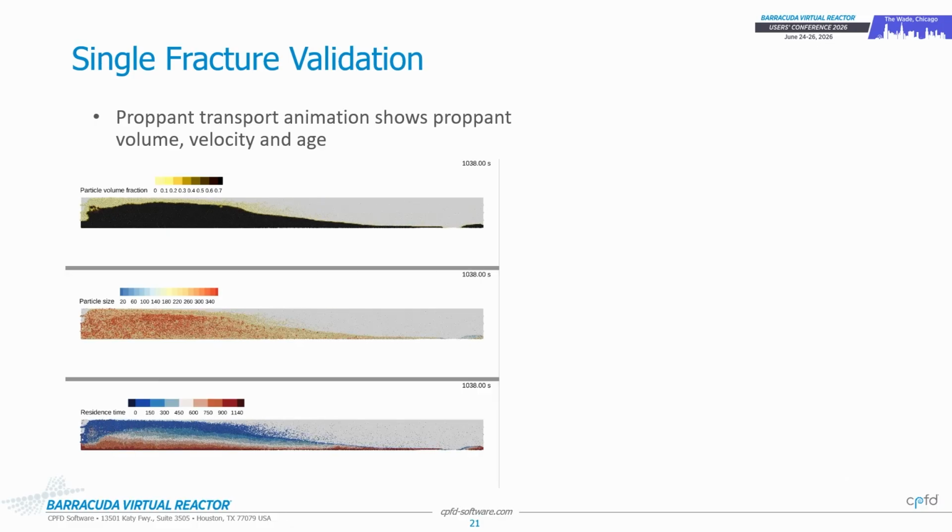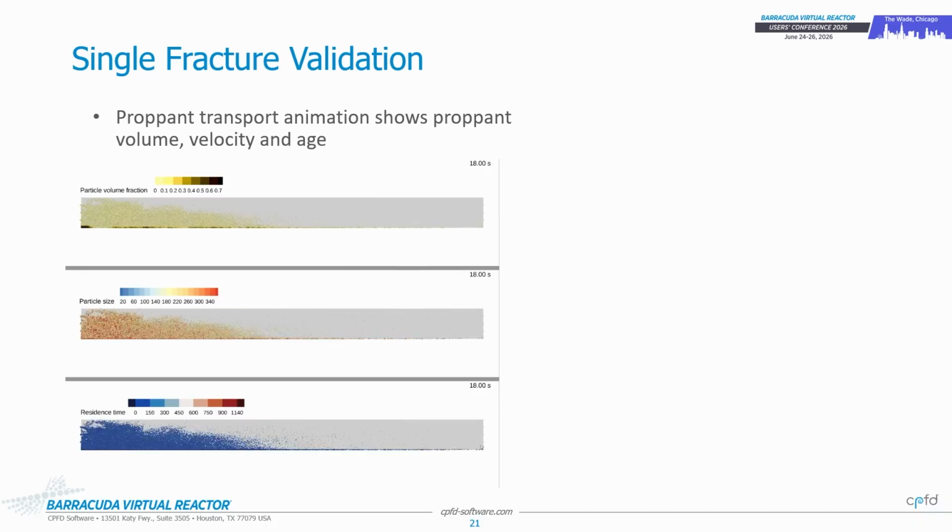You want some of the larger particles to settle down and pack completely till the top of your well down here, because this is a region where you're going to pull oil from, so you want to pack it as high as you can. But some of the lighter proppants, right, or some of the smaller proppants, you want them to settle down further. So that's why you have a PSD, and you can play around with multiple sands down there. You can plan your job, first 10 minutes this size, next 10 minutes the other size, I'm going to change the flow rate, and so on.